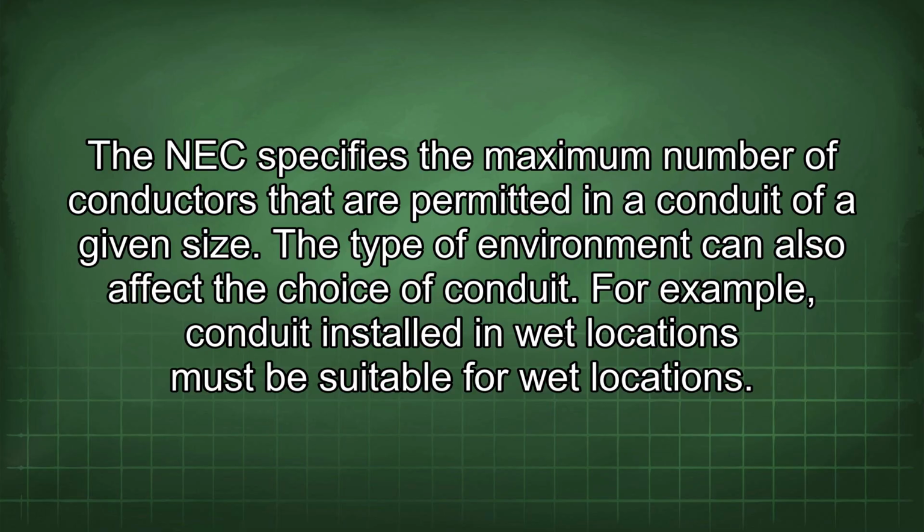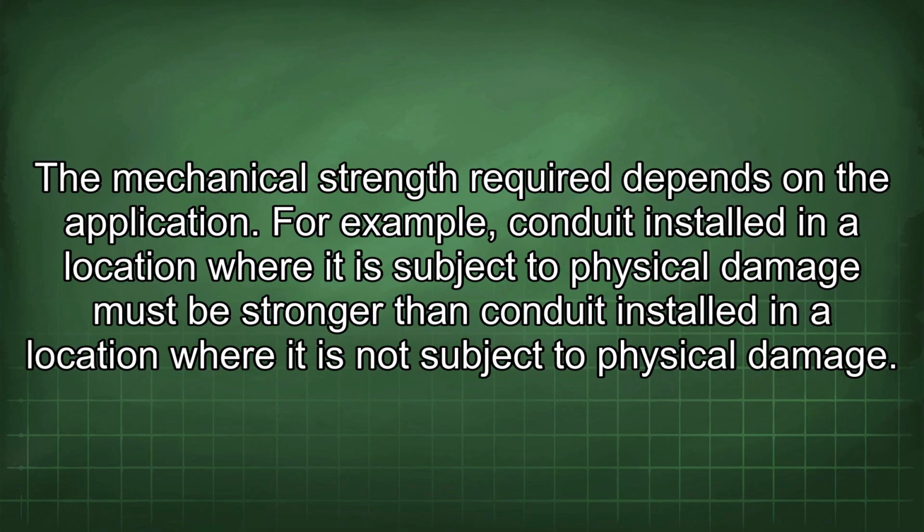The type of environment can also affect the choice of conduit. For example, conduit installed in wet locations must be suitable for wet locations. The mechanical strength required depends on the application. For example, conduit installed in a location where it is subject to physical damage must be stronger than conduit installed in a location where it is not subject to physical damage.